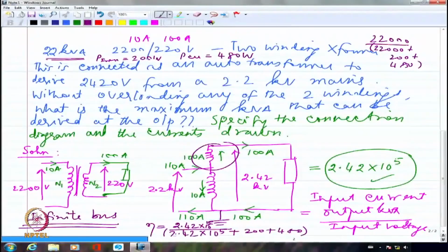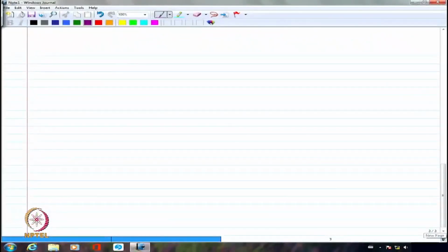Right? So auto transformers definitely are very, very good when I have strengthened the insulation to a sufficient extent. If I have not done that, the transformer will be burnt. It will be very, very difficult for you to make the transformer withstand the summation of both the voltages. That will not be possible. Right? So, to summarize, auto transformers are good, especially when I want to regulate the voltages by a small fraction of the total voltage that I am applying.